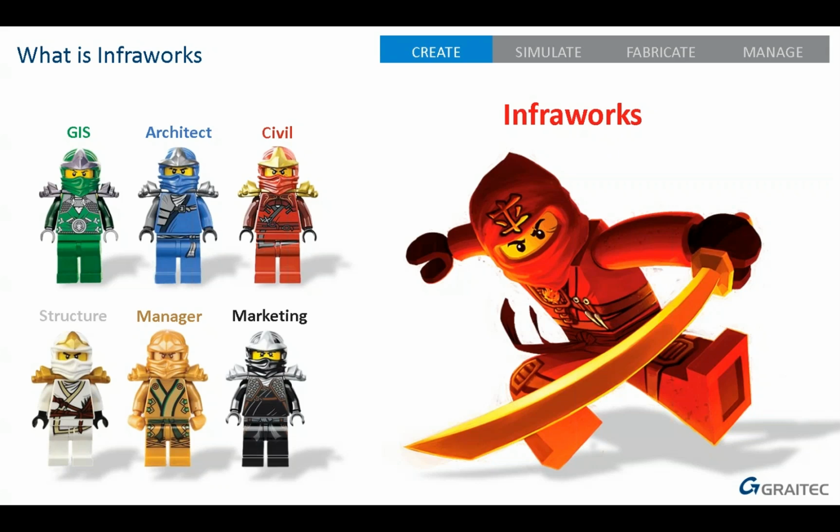It will place them automatically if they are georeferenced, which geospatial data will be, whereas your Revit models generally not, so you can manually place them. This doesn't replace Navisworks though. Doesn't do clash detection or anything like that. It's just great for early stage design. Get all your stuff together and work out your project.